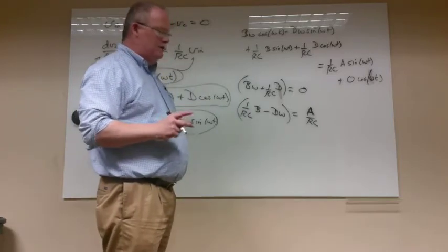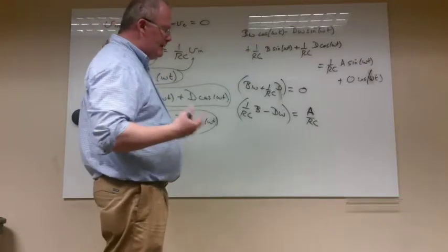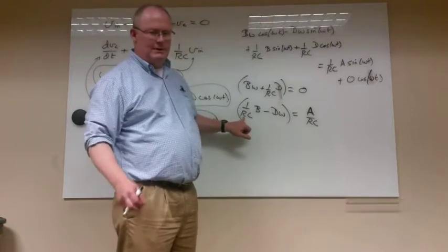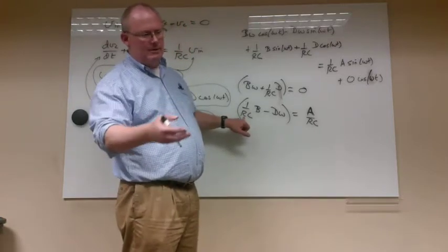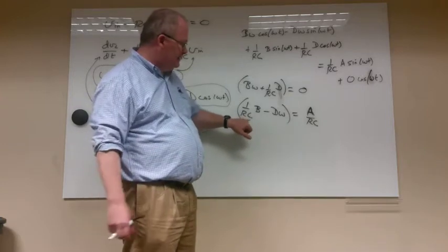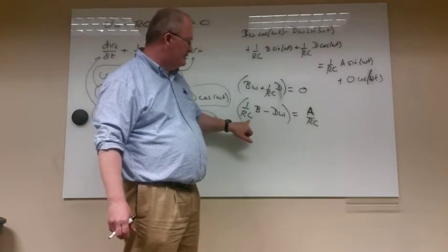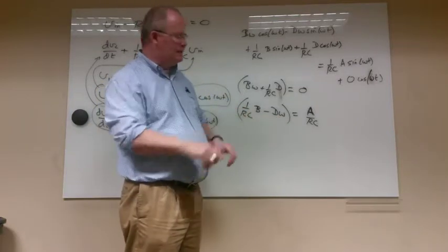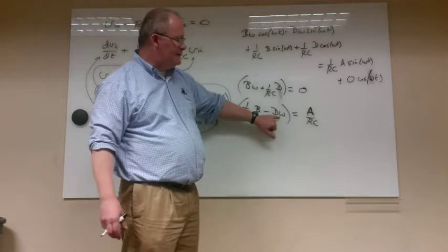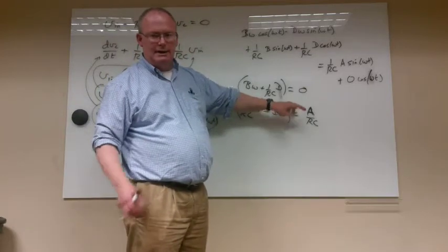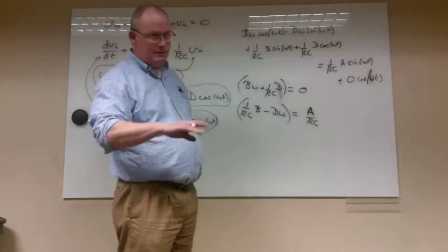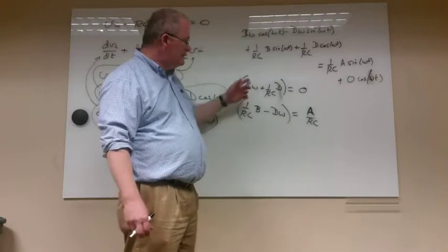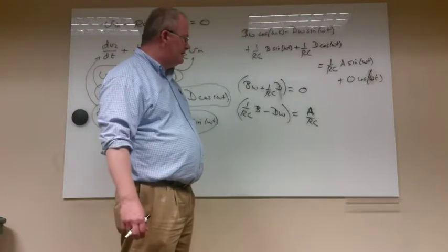So now we've got two equations and two unknowns. You might look at it and think, oh, a lot more than just two unknowns. Well, I don't really. R was fixed. You grabbed that out of the drawer and plugged it into the system, or had it on your breadboard, but it's fixed. Capacitance was also fixed. Omega is the frequency of excitation, where you would turn the dial on a function generator, except in your case you're typing it in. A is known. That's the amplitude, how big that sine wave was, from 0 to the maximum, or half of the peak to peak. So the only unknowns in these two equations are the D and the B.